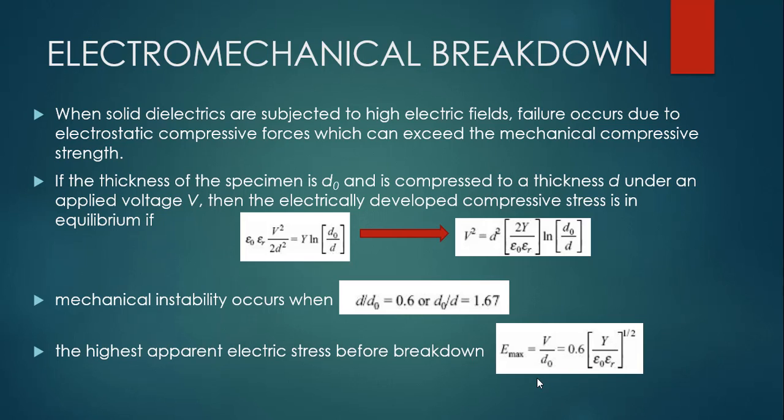There are thin cracks inside the insulator that propagate through the dielectric material, releasing both electrostatic energy as well as mechanical energy. So both electrical and mechanical energy take part in this mechanism. This is analogous to conventional mechanical crack propagation in brittle materials. If you see brittle materials breaking, the creation of cracks is similar to that, whereby the cracks propagate spontaneously if the strain energy released is greater than that required to overcome the toughness of the material.